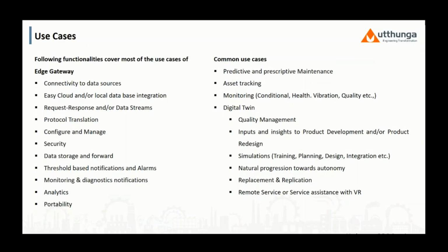In a typical IoT sense, it is not a store and forward, however, OPC has an inbuilt historical data access specification. As per that, the data can be historized, and whenever the client application or the cloud application recognizes that there is a disruption in the connection, once it comes back, it can request the missing data for that duration, and the OPC server can provide that missing data by responding to the historical data access requests.